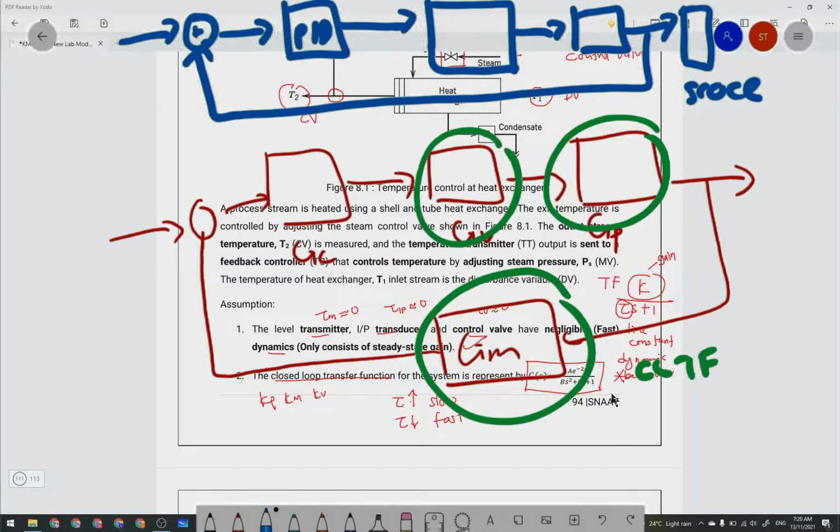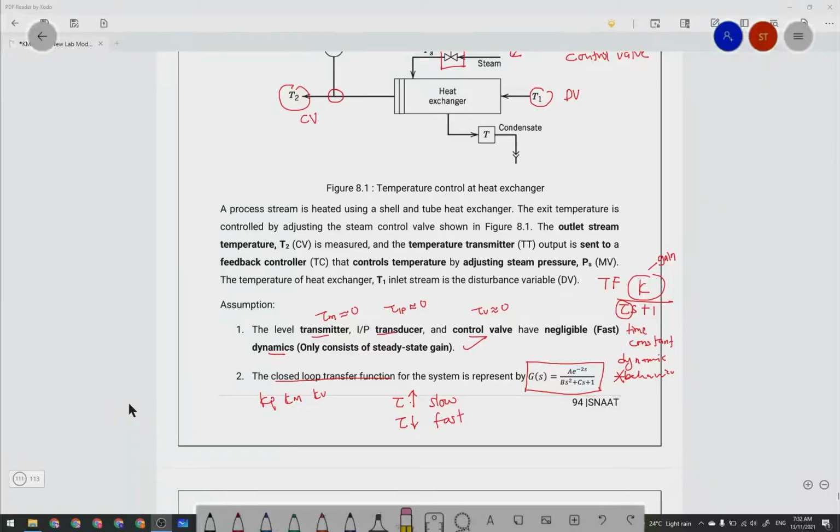Okay, plus minus. This we call a delay, and this is the closed loop transfer function, which is this one. As I mentioned previously, this value is a time delay. It means the system has a delay of about 2 seconds before it starts to respond. It's the same meaning as when I ask you a question and you take some time to respond, maybe due to the internet connection. That is also called time delay.